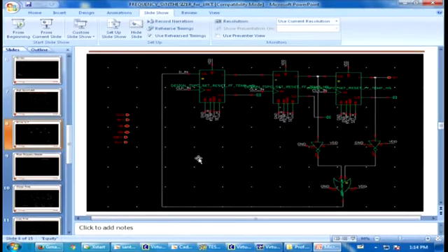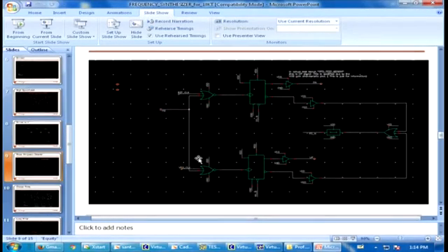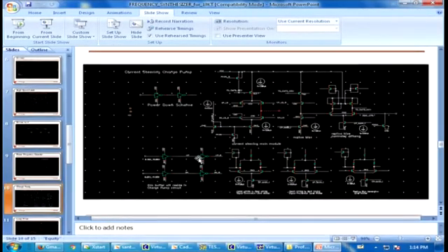It is divided by 5. This is all static kind of nature. This means CMOS logic is there. So these are operating at the lower frequency. As already sir told, when the VCO already has the highest frequency, like 5 gigahertz, the nearest divider will be the CML kind of technique. And when the divided down frequency is coming down, then you can go for the CMOS logic. CMOS logic static current consumption is 0. CML logic static current consumption is of course not 0, it's high, but it will give you higher speed.